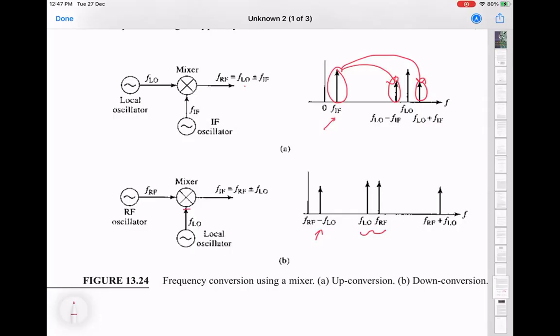So for example, if I'm speaking to you right now, all the information I'm sending is contained within maybe a few hundred hertz, around 500 hertz. So if I only send 500 hertz out of that, you're not going to make out anything. It's always changes. The change is basically what the information is. If you have only one frequency, you have only one thing you can send, the amplitude and the phase. But the moment you say that I'm going to now change the amplitude, that automatically means that there is a finite bandwidth to it, because you have to specify how quickly you're going to change.